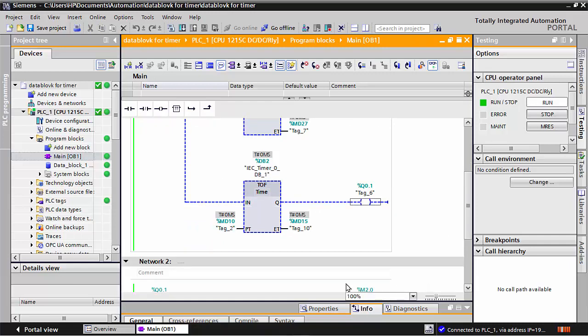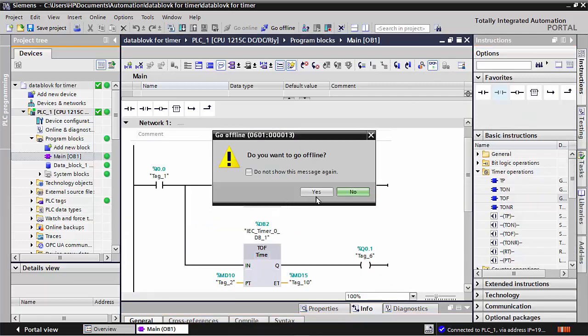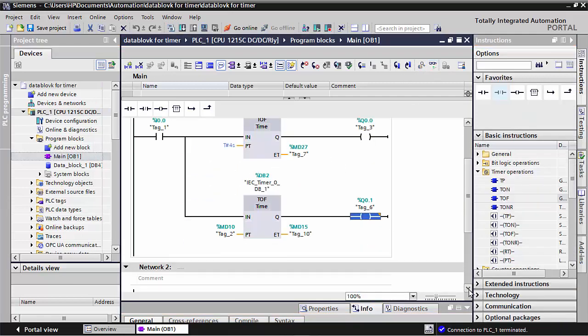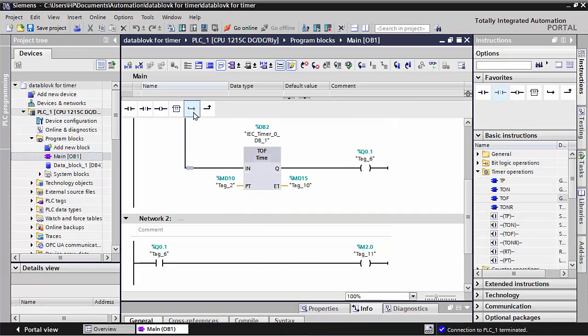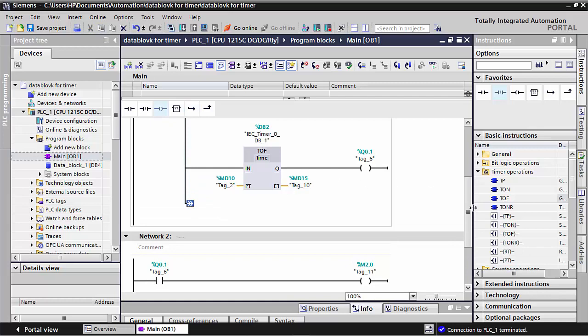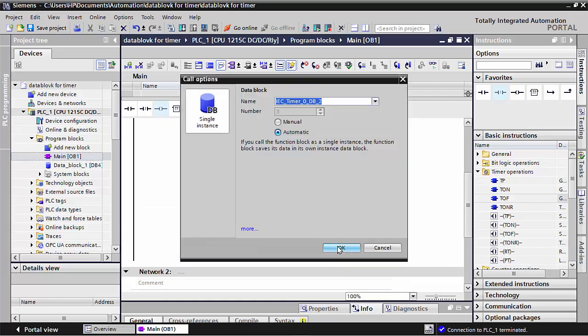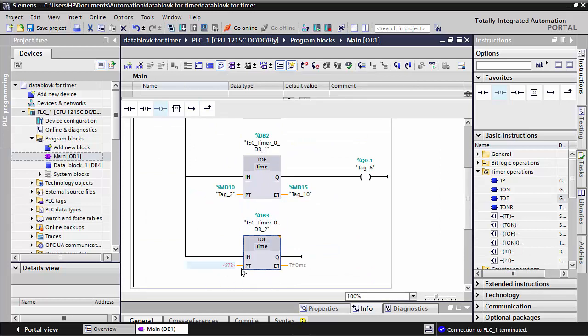You have to use data blocks. How to use data blocks? Stop the simulation and make one branch here, and these data registers I will use from here. This off delay timer can use, and also here you can see how many data registers you can use, and it says in this process time you can use DInt, time, double word, or DInt, yani you can use any.